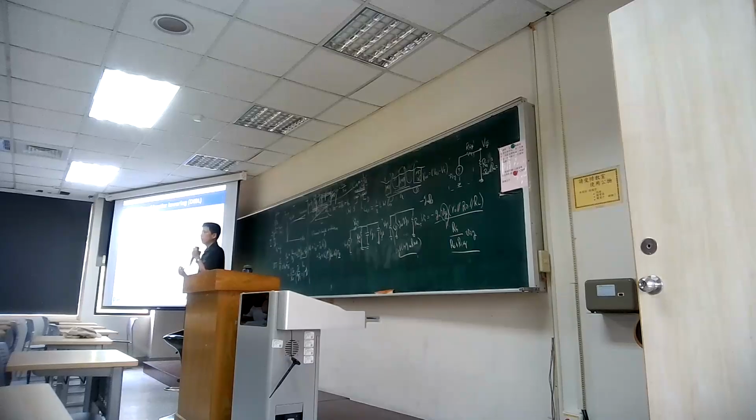So why can we improve the performance of your transistor even without shrinking the dimension? We can use a different structure. Previously we just considered a planar transistor that controls the channel from the gate on the surface only, but there will be some leakage current in the substrate, and also some other issues. But if you consider the FinFET, we get the gate around the fin. So we control the three sides of the surface of the fin on the substrate. So we are able to easily turn on and turn off the transistor.